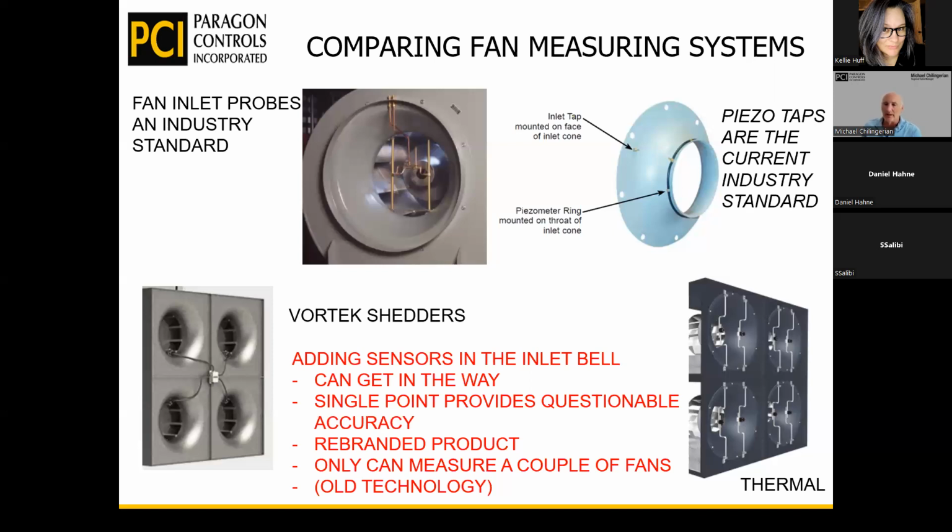In fan arrays, there's also the issue that every fan does not push the same amount of air. So measuring a small area or a fan, you might not capture what's going on. Basically, what these manufacturers have done is take their other airflow measurement products and rebrand them for fan measurement. So it's very limited in that it can only measure a couple of fans. If you have anything more than 8 fans, you're done with one of their devices. You have to go to multiple devices.